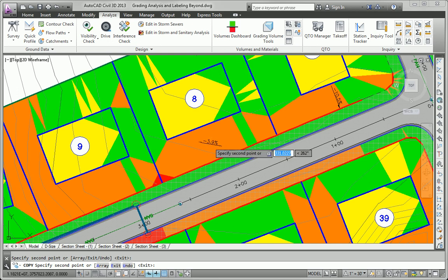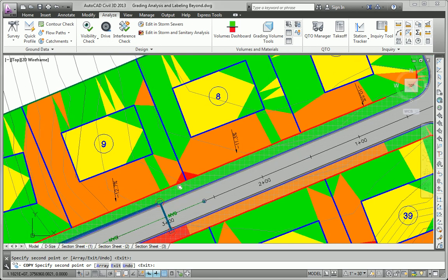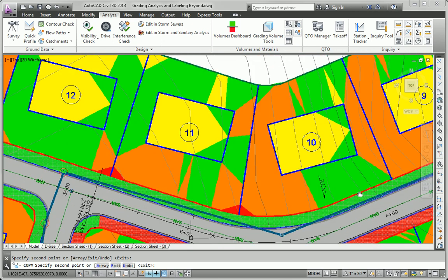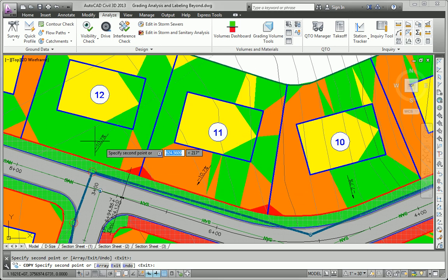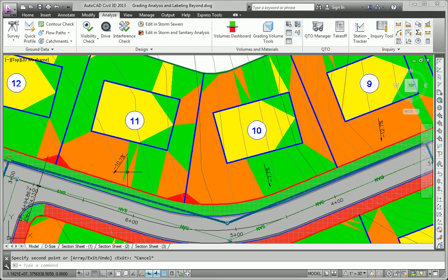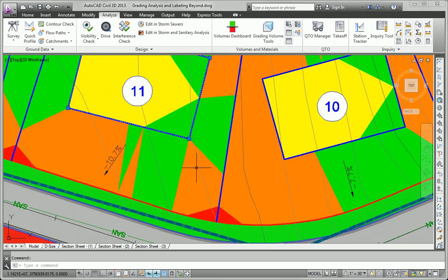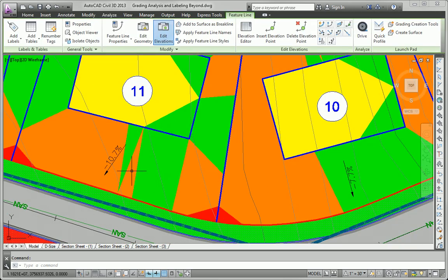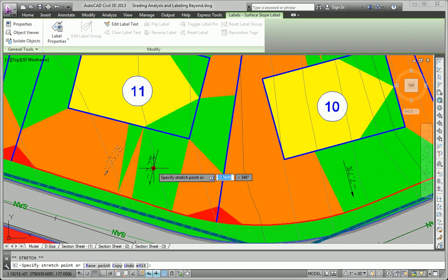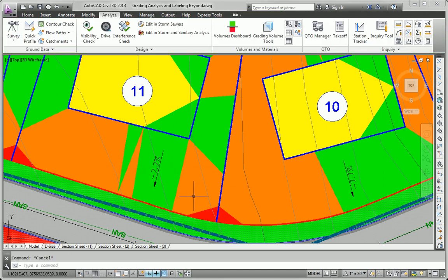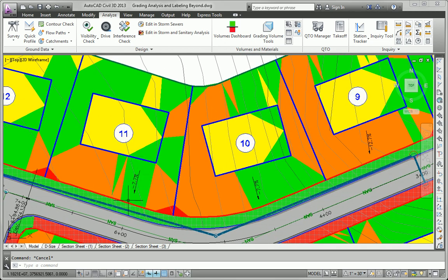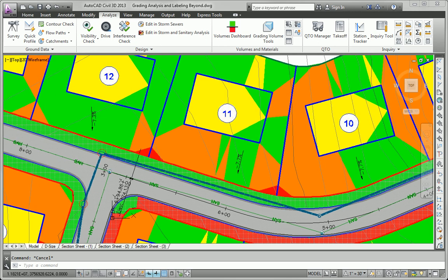and this is going to tell us where we've got issues. It's also going to tell our reviewers where we've got issues, and of course if our maximum slope in the front yard is 5%, we're going to need to address some of these before we turn it in. Or we could say, we're actually planning on putting our driveway over here. Let's say our maximum slope is 10%. There we're at 7.7, so we can say to the county or whatever the review agency is, this is where our driveway is going to be in this area.